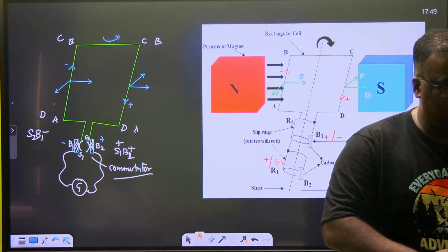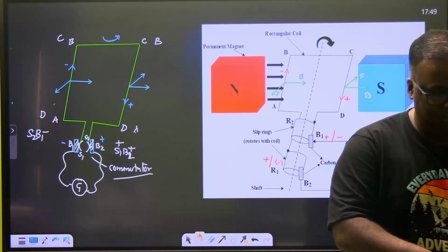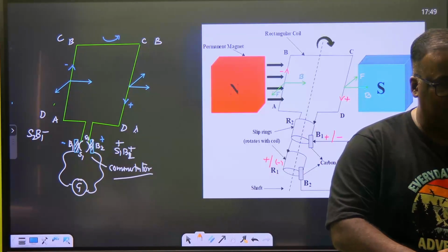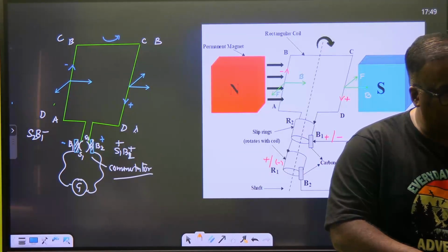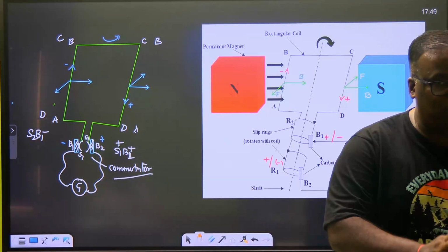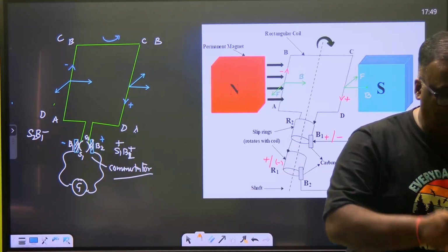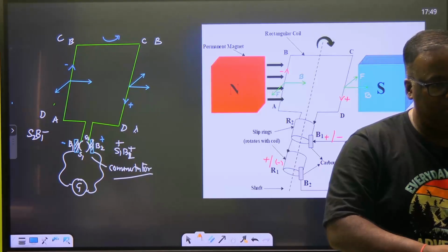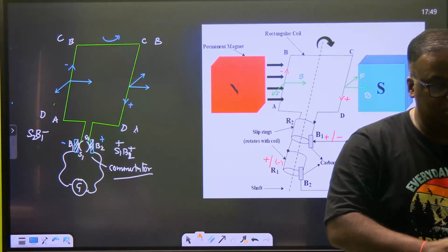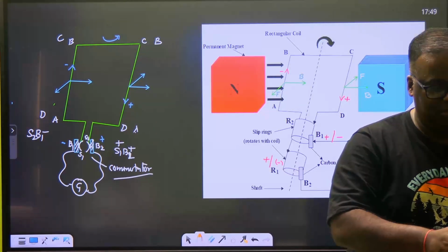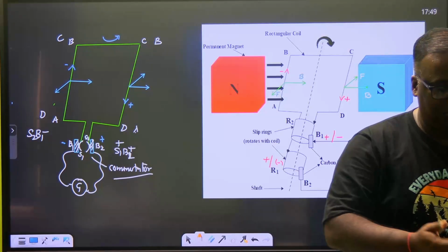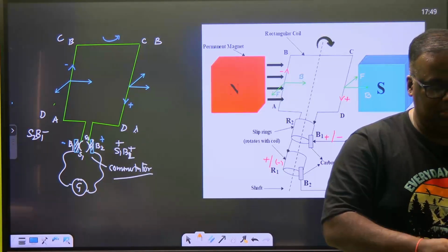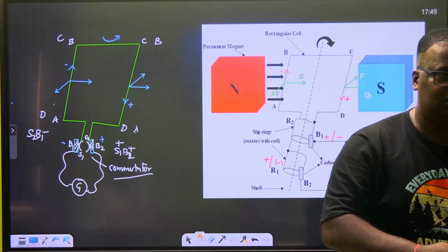This DC motor, let's make it a generator. If I turn this side also, current is getting generated, but this is an LED. LED is polarity sensitive. It will not glow. If I put a torch bulb, the torch bulb will glow. The faster the flux linkage, the more EMF is produced, the more current is produced. And this is the motor, and this is the generator.